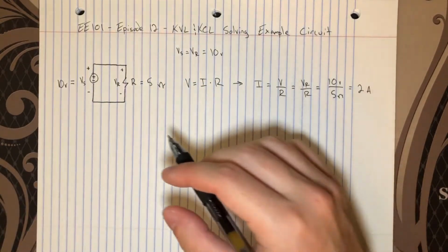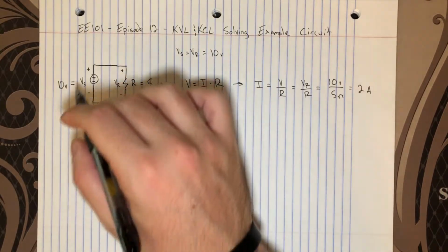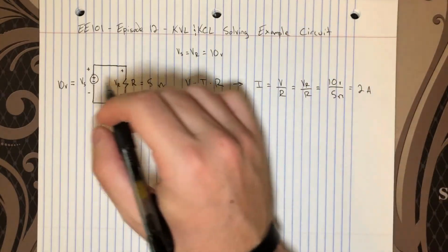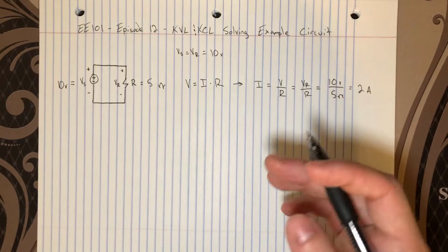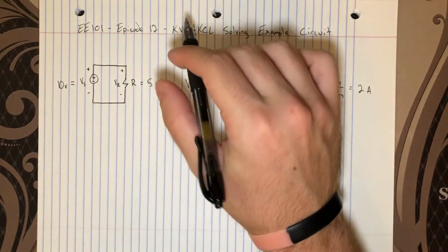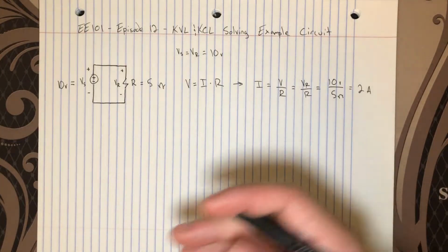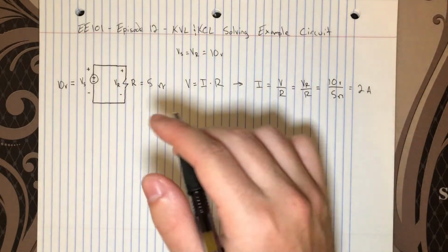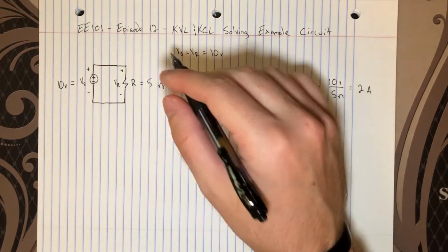And so you can see how I didn't even really need to use the words KVL and KCL in this case. I didn't need to step through that analysis of counting voltages or counting currents entering nodes because this is an ultra simplified case. It's only two circuit elements, and each node only has two directions that current can go. So it really is that simple, but it just goes to show that you can apply your intuition in a lot of cases. And I guess what I'm saying is KVL and KCL, the conservation of energy and charge, are really intuitive. And you'll start to pick this up and not necessarily need to step through rigorous calculations every time you solve a circuit, at least in these simple cases. So just remember that. What we're really doing here with my reasoning and intuition is KVL and KCL.